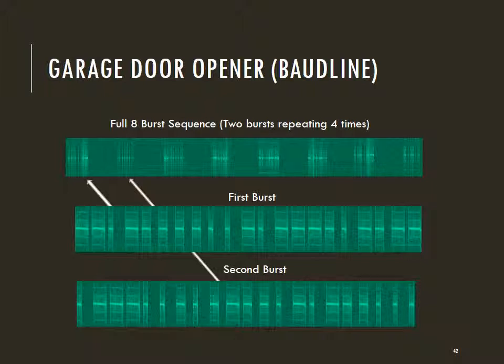You can see that this is a much simpler signal than the one transmitted by the key fob for the vehicle. Note that there's no continuous carrier transmitted this time. It is essentially on and off. And there seems to be a fixed width between each burst, and the bursts appear to have approximately 3 different lengths, and we can only assume that these correspond to bit values.